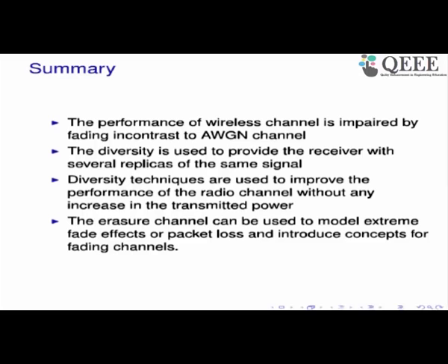Then we tried to get a general model of the MIMO channel, and then we showed a simple model of a flat slow fading channel. That is a channel that is invariant to change in time for the duration of interest, and second, all frequency components of the transmit signal go across the same fade.